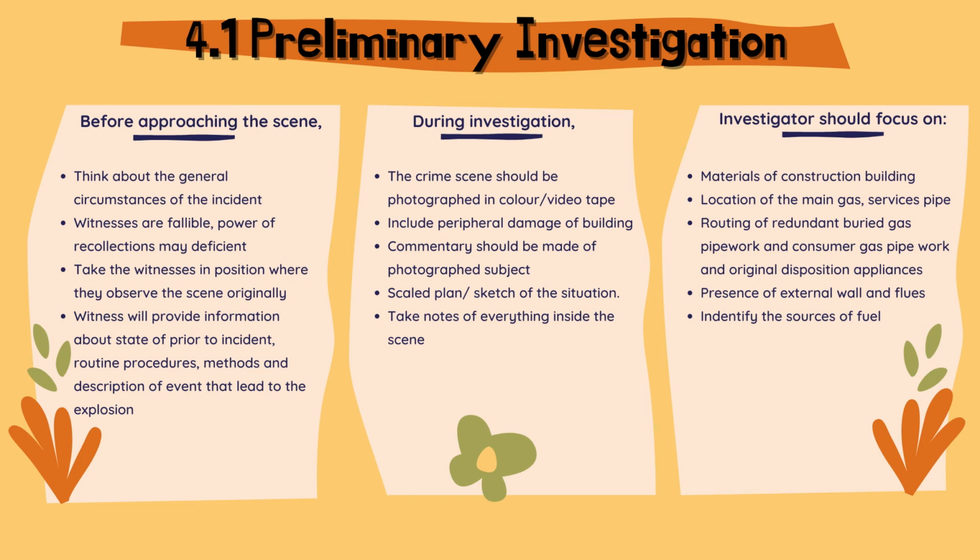Include peripheral damage to buildings. Written notes and commentary should be made of each photograph subject. Make a scale plan and sketch of what happened in the building or the situation. Make sure to take notes of everything inside the scene. Third, the investigator should focus more on the materials of construction of the buildings, the location of the main gas and service pipe, the routing of redundant buried gas pipework and consumers' gas pipework, and the original disposition of appliances. Note the presence of external walls and fuses, and identify the source of the fuse.